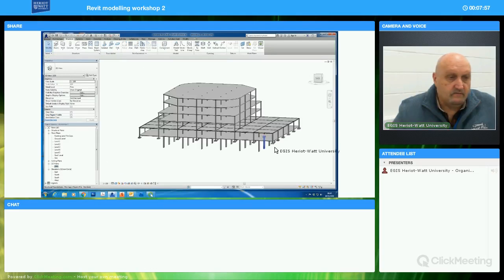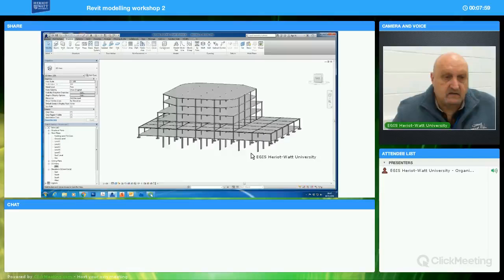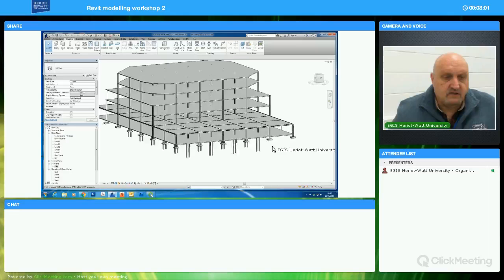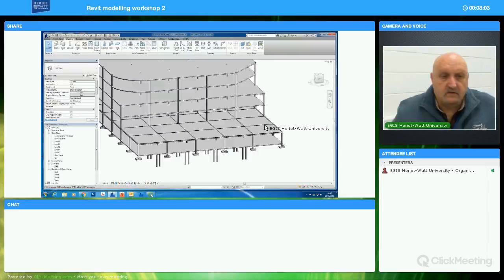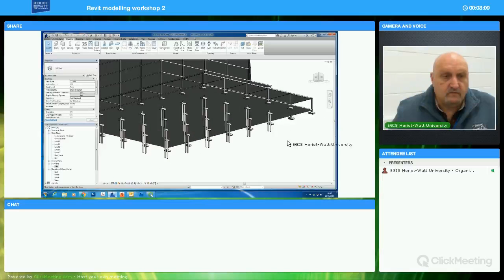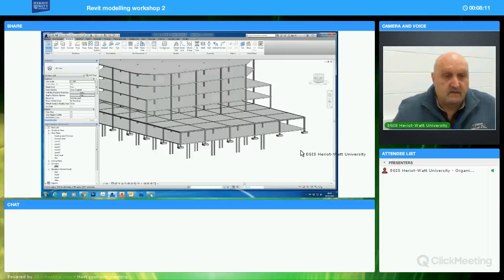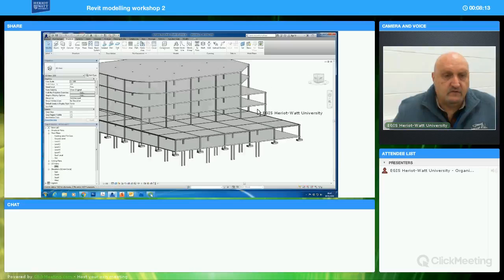And if I have a wee look at them, you'll see that basically they're in the wrong place. They use the same 3D space as the floor. Clearly the beams are going to be set underneath the floor to provide the support for that floor. They don't occupy the same 3D space. I have a further edit to do on these floors.